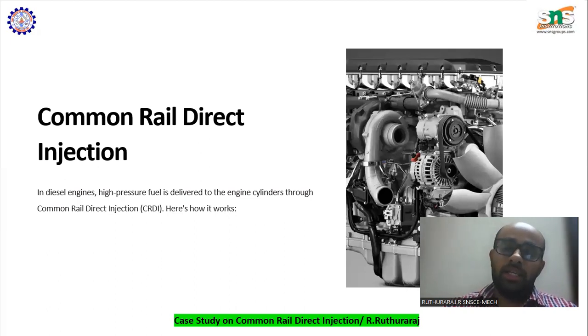But if you take larger machines or larger engines, say the case of a diesel engine in a train or a truck or a ship. Most of the ships run on diesel engine. Some may run on coal and others on nuclear fuel, but predominantly most ships run on diesel engine. High power and high torque can be obtained through diesel engines. That's the reason the preferred mode is compression ignition.